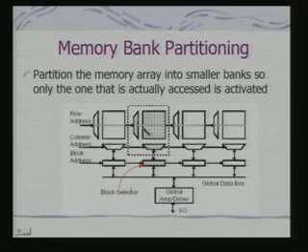Then the corresponding cell that is being made use of and the other circuitry lead to much less power consumption, because your lines are not driving all these cells at the same point in time. Charging and discharging of capacitors on the lines is really eliminated the moment I go into smaller banks. So, SRAMs are typically expected to be organized in terms of these smaller banks to optimize power consumption.